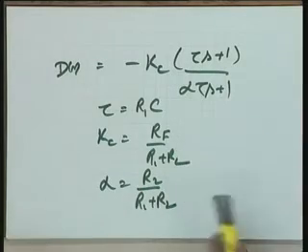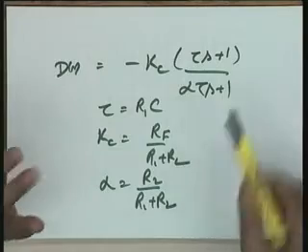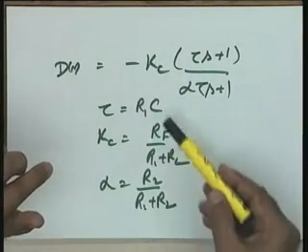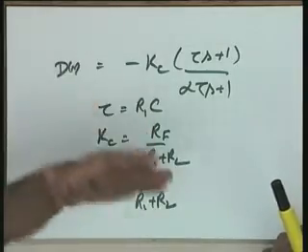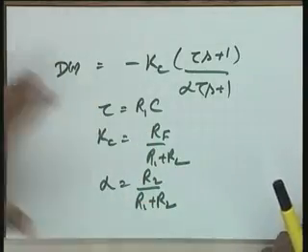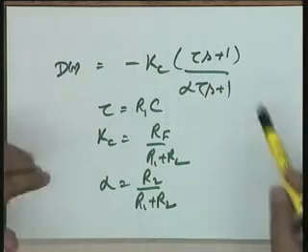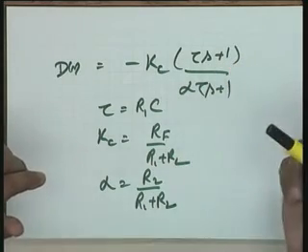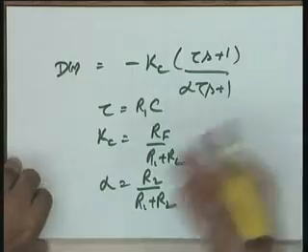You see, in this case the design freedom is there, not that it is one-to-one relationship. You know three parameters. Using these three, and here there are four selections, C, Rf, R1 and R2. So depending upon suitable values of devices from considerations other than implementing the values, you have to suitably select the values. The design freedom is there. You have more freedom than the values required, and hence one of the values could be taken and other appropriate values of resistors and capacitors are taken. Okay.